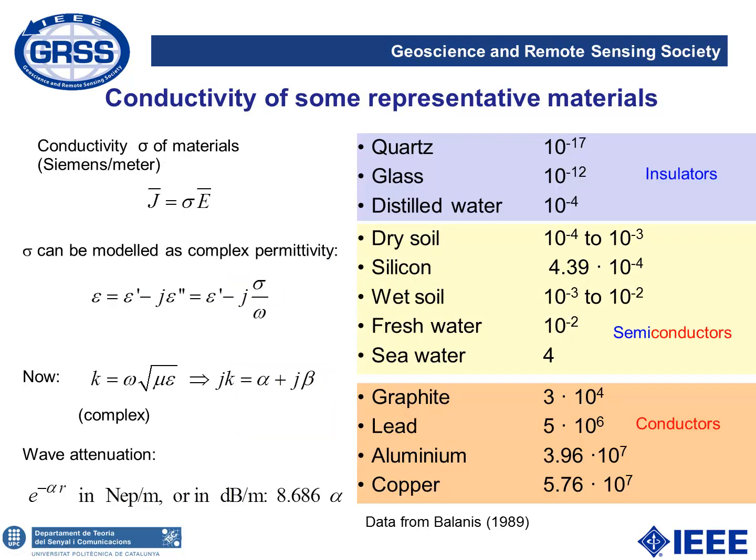What about the conductivity? The conductivity is the capacity of the material to develop electric currents inside the material in case of electric field excitation. And actually these electrical currents are responsible for losses, typically in dielectrics, and these losses can be modeled by including an imaginary part in the dielectric permittivity of the material.